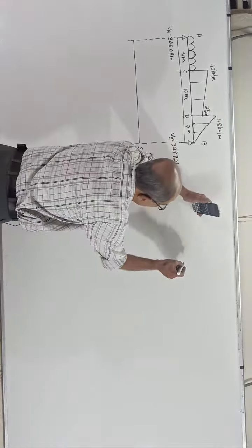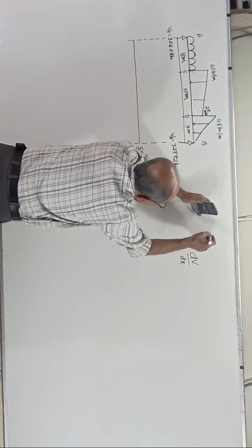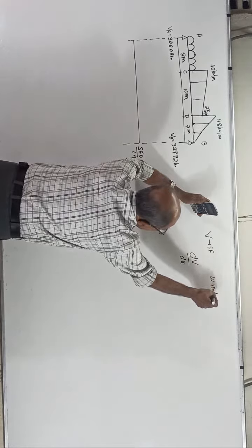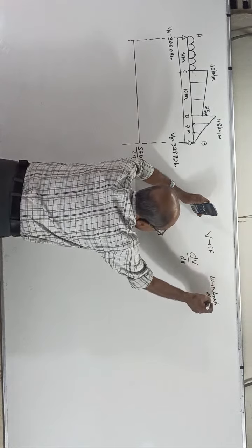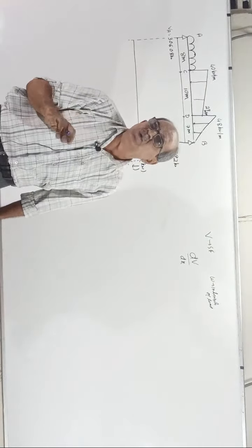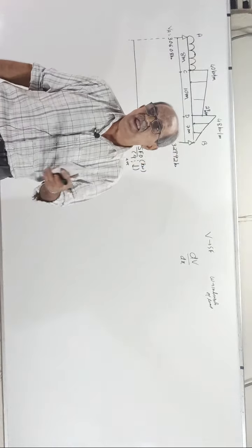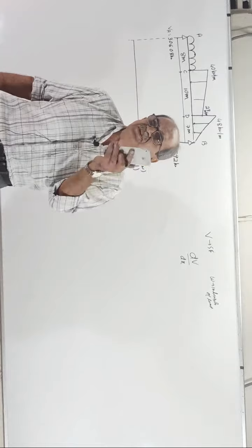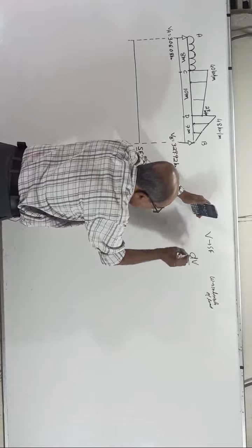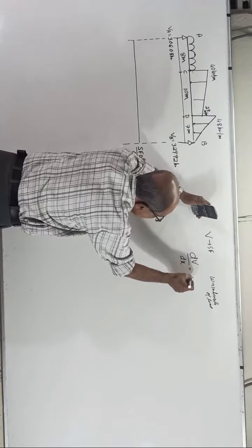Last I will tell, remember, dV by dx. See, V is shear force. w is intensity of load. Intensity of load is valid only for UDL and UVL, not for point load. Point load, sudden change. But actually, even for point load, in class number 100, I have given a lot of principles there. When you write dV by dx, you should know one thing. Rate of change of shear force is intensity of load.